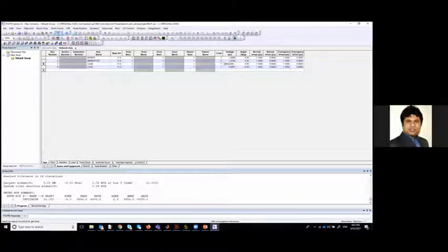But if you look at the bus for the load, for the generator we know P and V, but for the load we know P and Q. That means we need to find V and delta. If you look, the load bus voltage changes and the load bus angle also changes after the power flow. And the generator rotor angle changed, but for the infinite bus it has not changed. The generator rotor angle changed, but the voltage is the same.